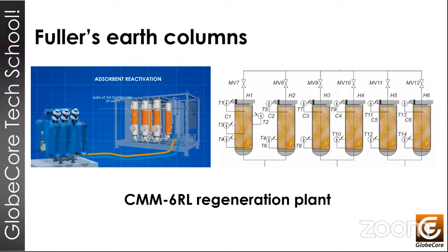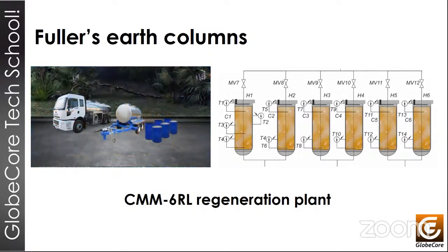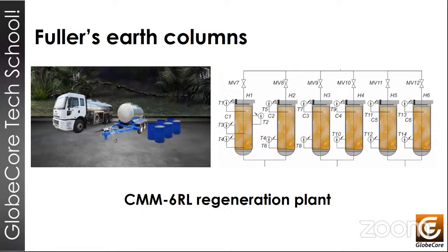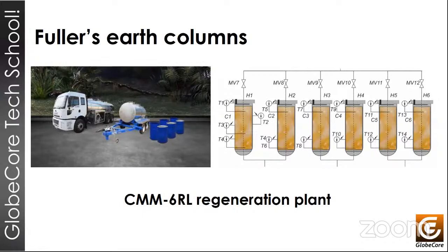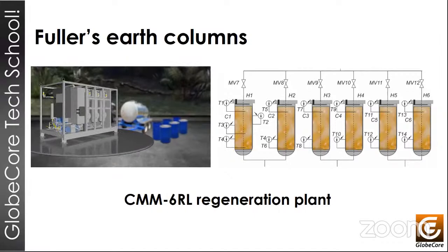If the temperatures are exceeding a certain limit, that means we have a problem, or temperatures are cooler than we expect, and maybe the process is not going right as well. So one column has, I think it's 6 sensors, and the rest have only one. One column is the control column, and we assume that the process in the other columns runs pretty much the same as in the first control column.